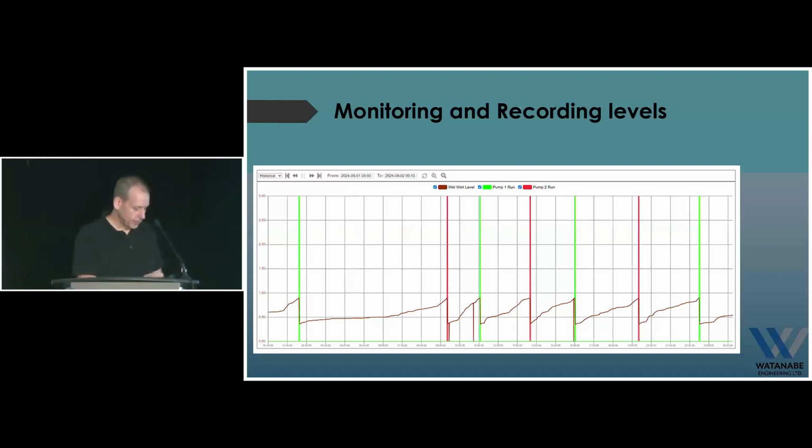So we're just going to go through a few things here in terms of what we see. We get a nice long run here. You can see a nice steady climb. This is the early hours of the morning, and then we move into more of the day, where we're getting the closer pump runs. So this is kind of typical. One of the things you'll see though, if you get a rainy day, all of a sudden these get really tight. They start to become really quick pump cycles and quick fill times. So that's a good indicator if you've got I&I in your stations.